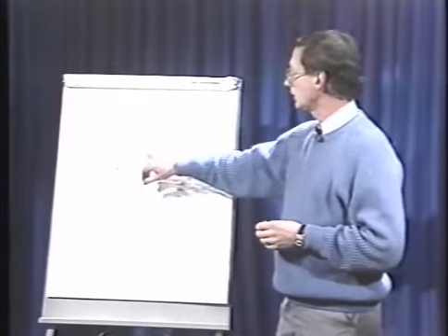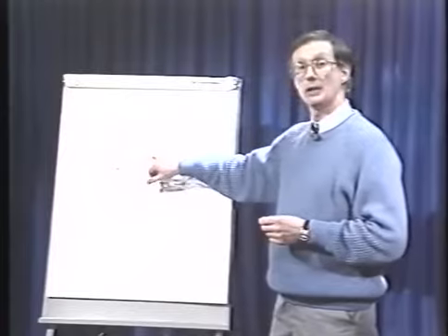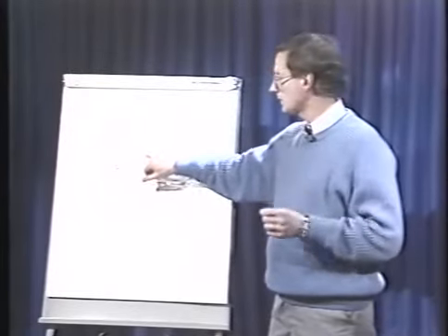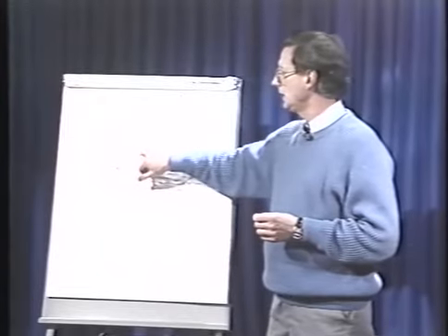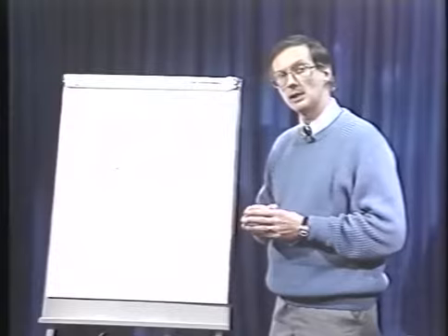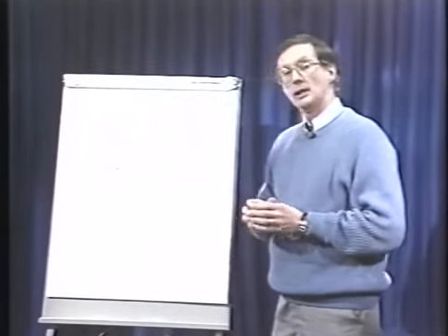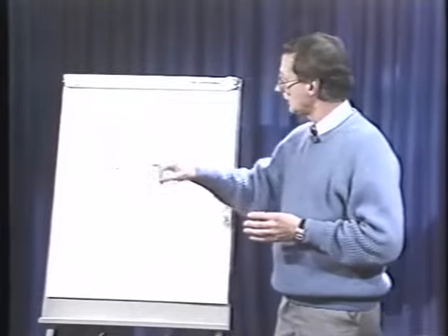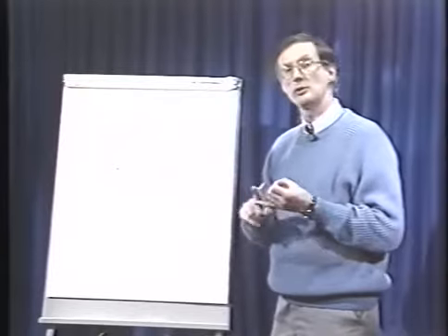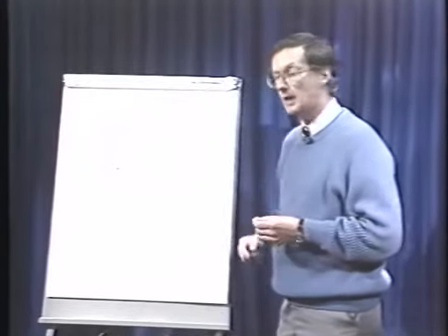The incremental control on a wire feeder may state 0 to 100 or 0 to 10, but traditionally it's in increments of 10, which means each control increment on the wire feeder is approximately 70 inches a minute or 30 millimeters per second. Let's look at the relationship again of the wire feed to the amperage to the short circuit requirements as it relates now to an 035 electrode.